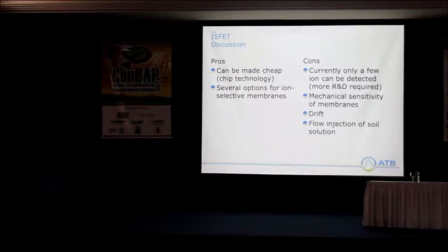And there are several options for these membranes, but only a few are available right now. These membranes are sensitive. Also, these sensors tend to drift. And in most cases, you need to construct something for flow injection of soil solution, which makes the handling again complicated, more expensive.